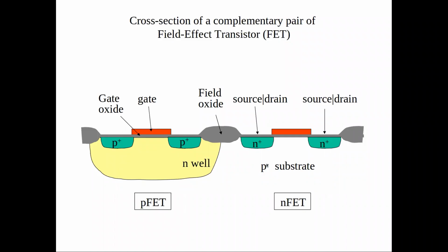So it's lightly doped if there's a minus. You could have N minus, like here it could be N or N minus, or P minus or P plus and N plus. So the plus and the minus are not referring to the charge, but to the amount or intensity of concentration. Depending on the P and the N, you have a P-type or a P-FET or an N-FET.